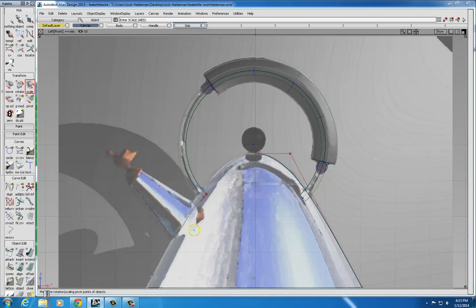3 is still too small, but we can now scale it up and get that thing to be about the right size of the base of the tea kettle. Now we may need to scale that up or down, but let's check it out. Let's see how far we can get. Next thing, I'm going to rotate it, and this time I can rotate it around either the X or the Z. It really doesn't matter. I need to rotate it again anyway, so 90, 0, 0 gives us that.